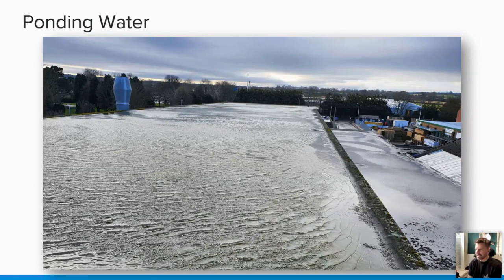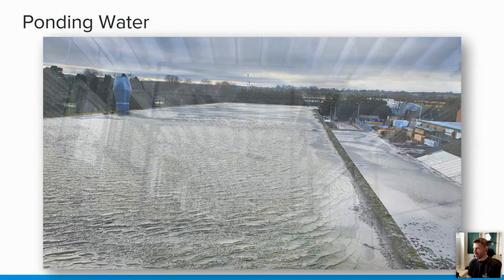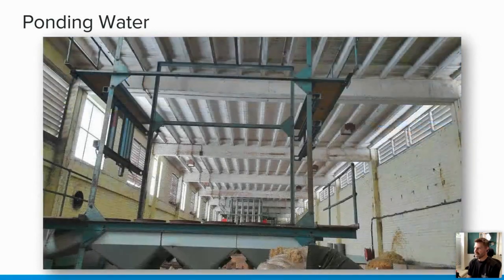So we've got about 20 kilograms per square meter of additional load on this roof. You can see the outlets on this one are down the perimeter of the roof there. You can just see one about 3/4 of the way up the picture. But the falls are actually now going away from those outlets. And when we look on the inside of the building, you can see the effect that it's having.